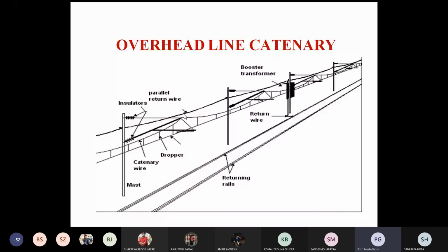That is also a small type of substation. That substation normally consists of some CT as well as some PT. For individual phase lines, the CT is directly connected with the substation, and the PT is also connected directly. The CT is connected in series with the line, and the PT is always maintaining how much voltage is there. So what is the purpose of the PT? To calculate how much voltage level is there in your line.